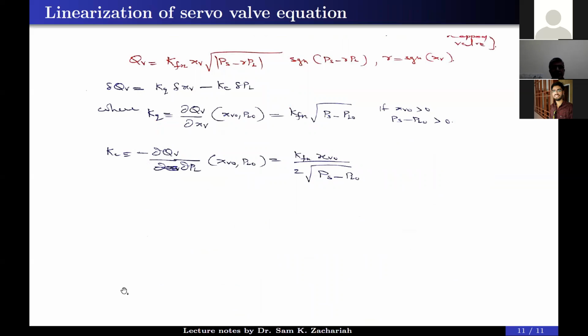Okay, this is now another part. So far we have been discussing the total nonlinear model. But when we start any analysis, we start with the linear system model, do some transfer function analysis, and validate our linear model. Only then will we introduce nonlinearities and analyze the nonlinear effects. Here is one problem, unlike our electromechanical actuator, where if you simply remove the friction and saturation, you can remove all nonlinearities.